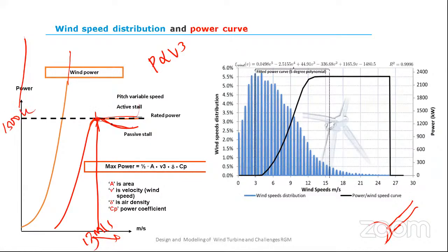But when the wind speed increases, the stall control machine is stalling the turbine. It means that the power is reduced. Why this? Because I have to reduce the speed of my turbine. It is a control mechanism. You have to design the control. It has been designed, the control mechanisms to limit the power of the rotors. Then once they limit the power, it automatically reduces the power, and when the wind speed is reduced, automatically it will go back to the normal position.